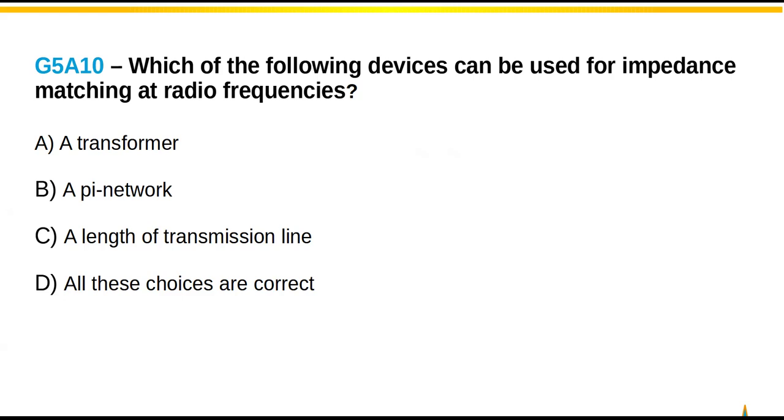I mean, if you look at a typical 7300, to put 100 watts out, you need 22 amps at 13.8 volts. Well, just figure out the wattage. It's a lot more than 100 watts. Okay.